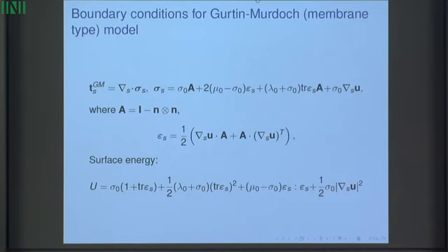If you look in the literature, you can see that there are some curtailed Gurtin-Murdoch models. So this is a full model, but sometimes you will see problems where people drop this term, or more rarely drop this term. So it's kind of modifications to the model. There are again lots of papers dedicated to this particular type of surface traction TS.